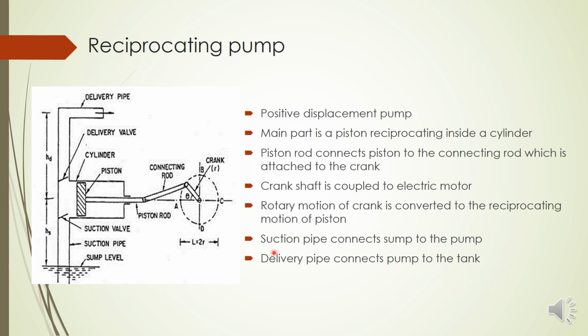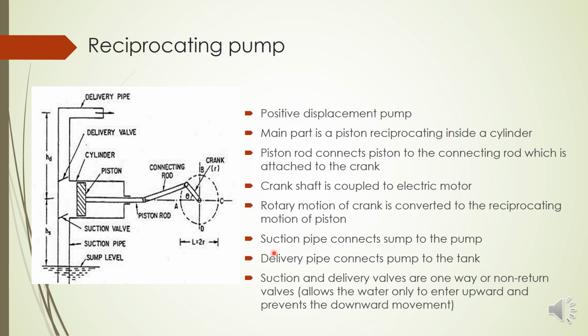And what are the remaining parts? Yes, two valves are there. You can see here a suction valve at the entrance of the pump, and similarly a delivery valve at the exit of this pump region. And the peculiarity of these valves is they are one-way valves or non-return valves.